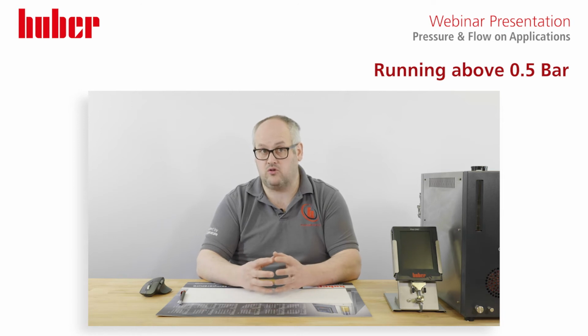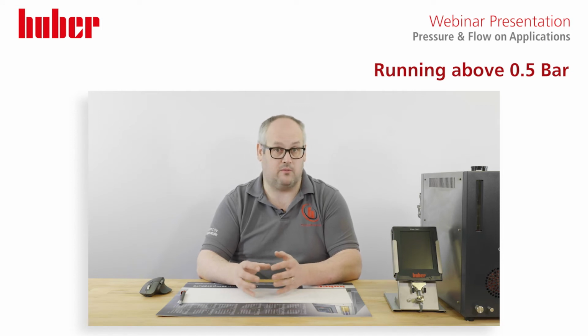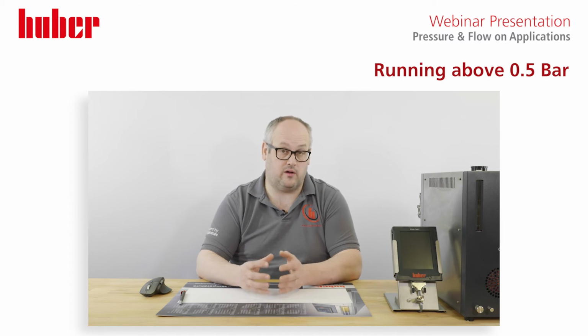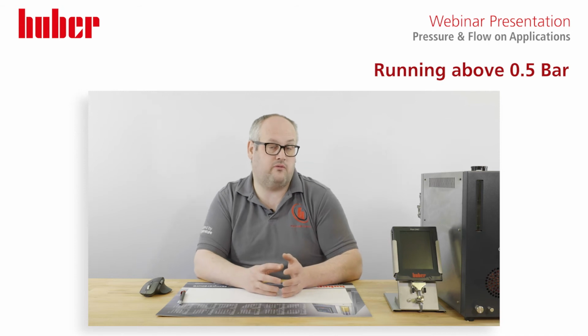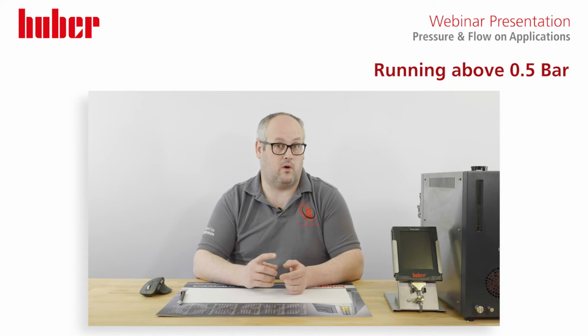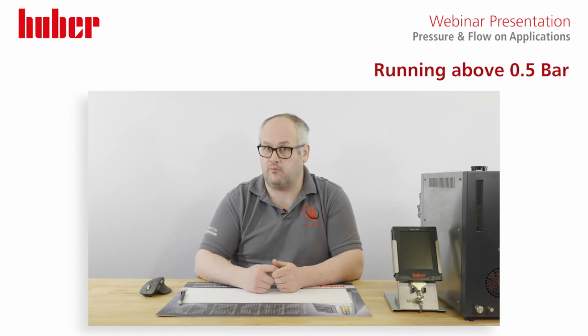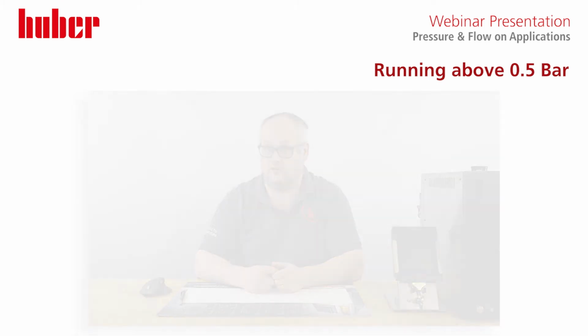So if we had a truly sealed system and we're either A, warming up from a cold temperature, or B, heating up from room temperature, the oil would expand and would apply a hydraulic pressure onto the glass and would cause it to break. So to prove this a little bit further, we're going to look at two more things. We're going to look at number one, booster pumps, and number two, what is the true hydraulic pressure on a glass reactor and how it will actually break.